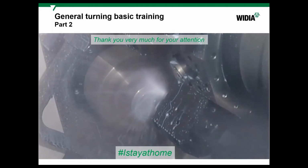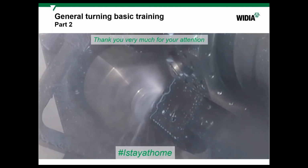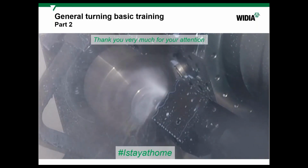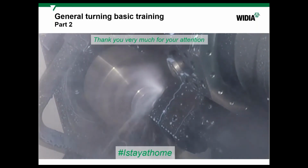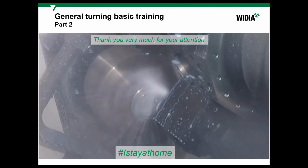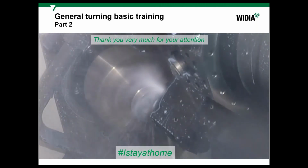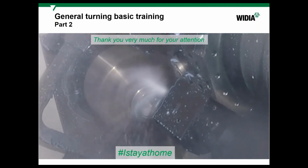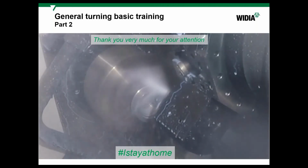So for negative inserts, if the hole is slightly big, it's a UR or MR geometry. For smaller holes, for example, 30 millimeters or even smaller, positive inserts like a CCMT or TCMT. But be sure that the holder with these inserts leads to an approach angle of 90 degrees. But usually WP25 should be okay for the start.